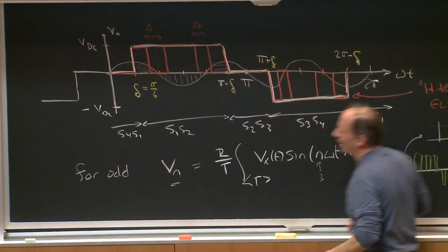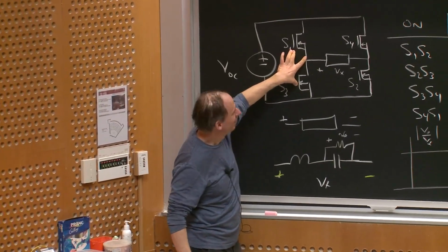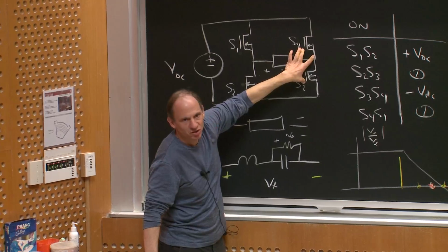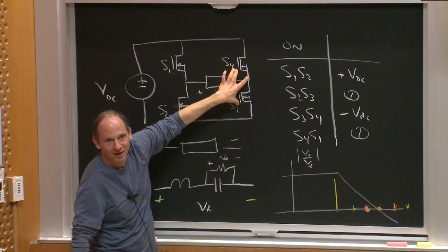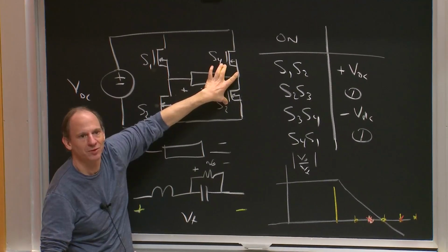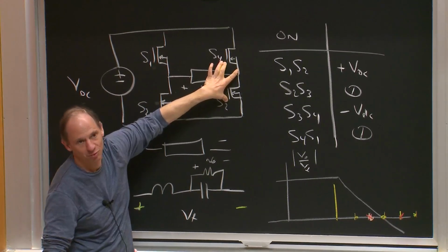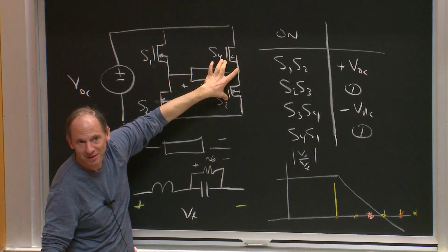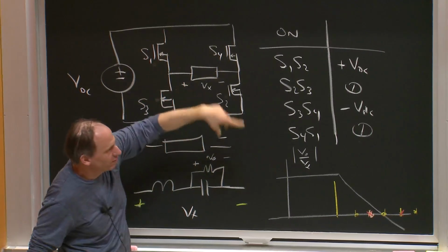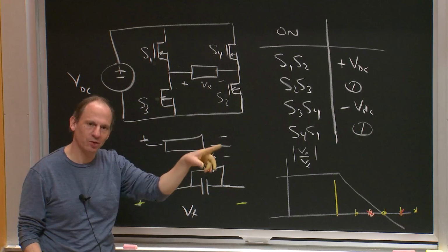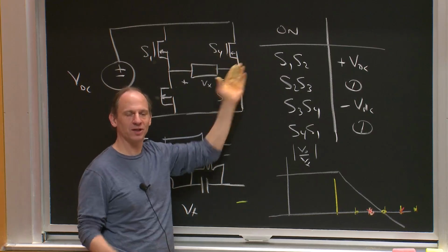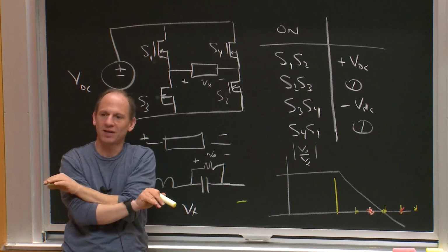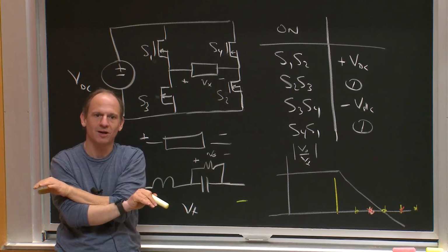what I could really view that as is 1/2 of this bridge generating a square wave, and the other half of the bridge generating a square wave that's 60 degrees out of phase at the fundamental, and at 3 times the frequency, at the third harmonic, or 6th, 9th, 12th, etc., it'll be 180 degrees out of phase. So in fact, the one pulse per cycle waveform that I showed you, you could really view it as a cancellation because I have 2 half bridges that are each generating square waves, and I get a harmonic cancellation between those square waves, killing the triple N harmonics.